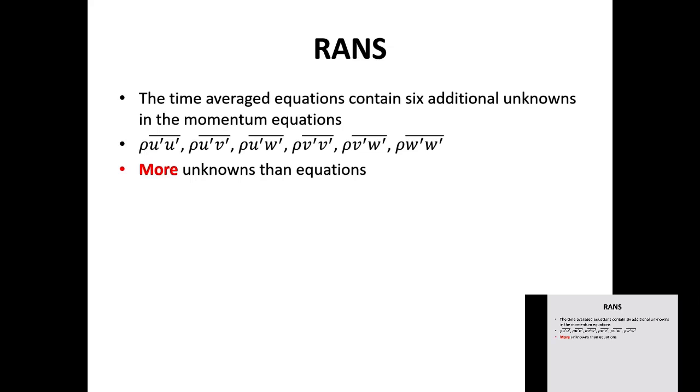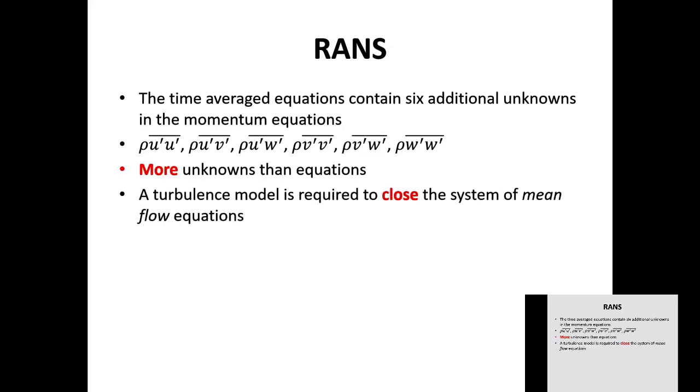But in the long run, the average velocities should be equal to U, V, and W. Even though the fluctuating component varies over time, the average of those fluctuations should be equal to 0. So when you define your u, v, and w, you will have additional terms in this form.